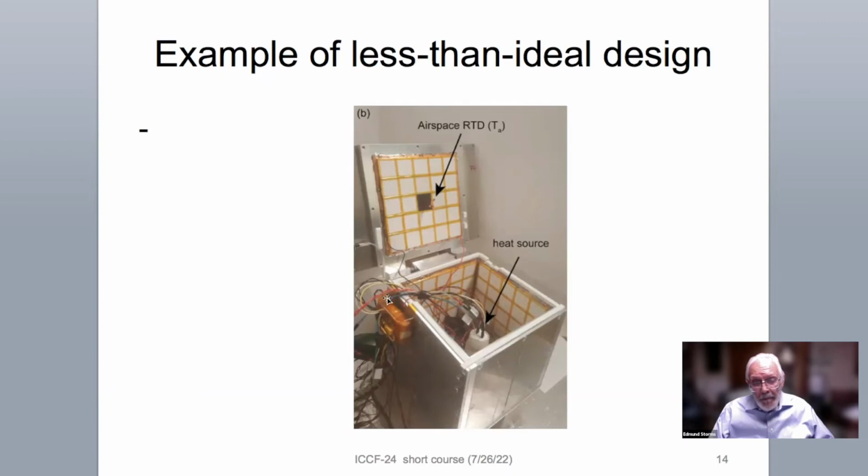sensitive to room temperature. It's necessary for any wire that leaves the calorimeter box to be thermally bonded to the box itself, so that the one end of the wire is now at a constant temperature. The calorimeter does not care whether some heat is lost to the box. It only cares that that be constant and independent of any outside source. So you do not want this kind of arrangement, because that makes the calorimeter sensitive to room temperature.